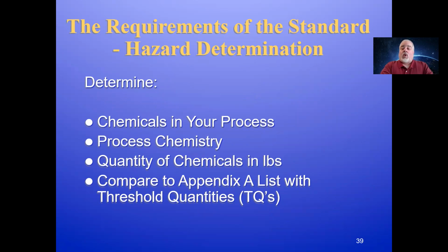Hazards of the process. Well, what are the chemicals that are a potential hazard? And it's not just the chemicals that require the PSM. There's something that throws you into the realm of PSM, but it's kind of a waste to think of this in isolation. All right, the only thing that's going to push our company over the threshold of PSM is anhydrous ammonia. So we're not going to worry about the chlorine, and we're not going to worry about the diesel fuel because it's only for filling vehicles and the chlorine doesn't reach threshold quantities.